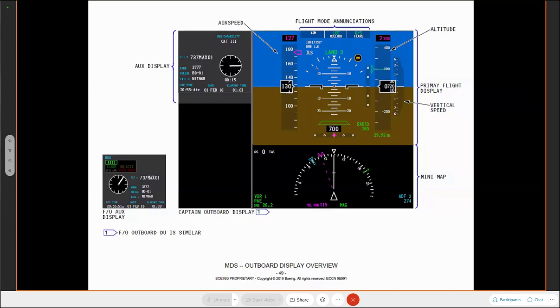The guidance source. In this case, it's ILS, because it's telling me here my source of information for guidance is ILS. If it was the GPS landing system, instead of saying ILS on there, it would say GLS. The MAX uses a ground-based augmentation system similar to the 787. The 777X is using what they call a satellite augmentation-based system. It doesn't rely upon any ground technology at all, but four fixed point satellites. Again, another step. So the aircraft is capable of GPS landing if you have it, as well as ILS.